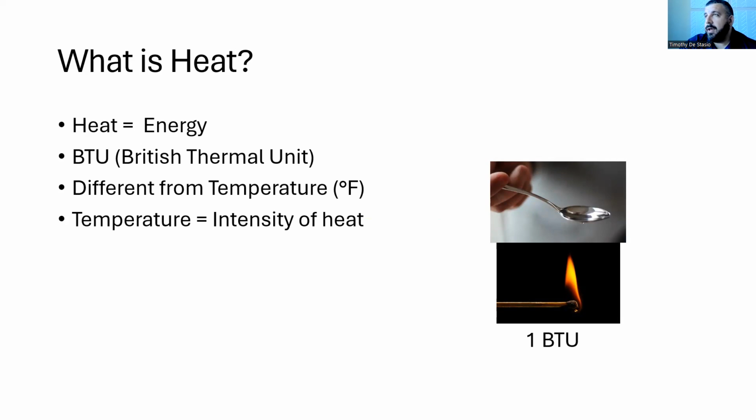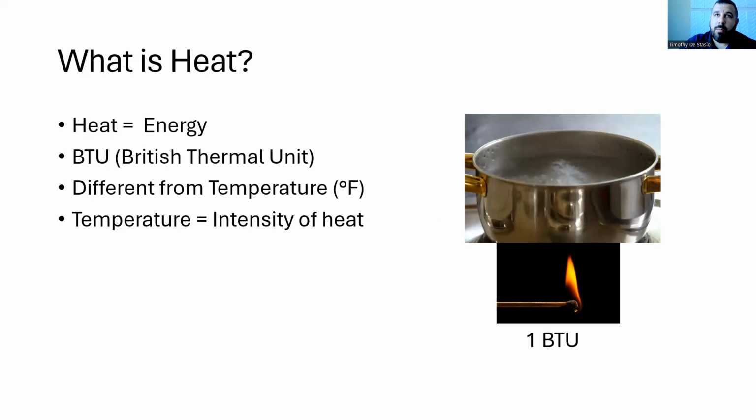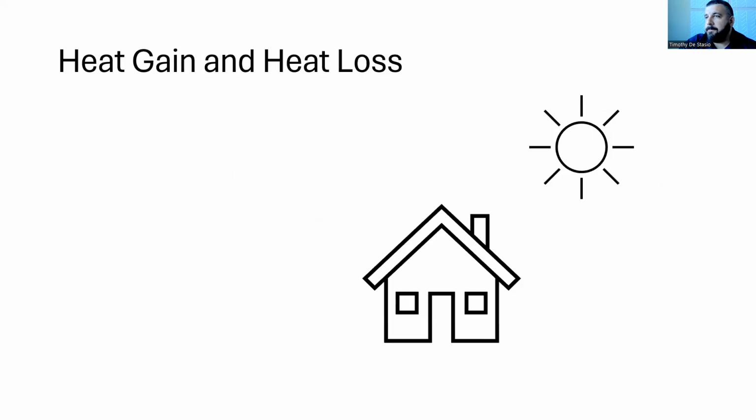By the time that match goes out, that water might even be pretty warm. But let's hold that same match under an entire pot of water. Could we expect to boil that water with 1 BTU? Absolutely not. And that's just because the intensity of the heat is spread out over a larger area. So again, we want to understand the difference between temperature and heat because we deal with both in Manual J.